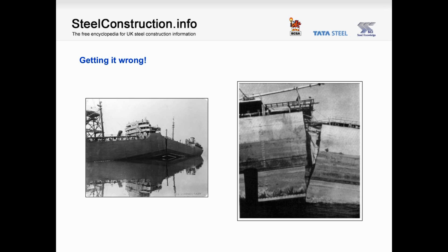It's also worth noting that there'd been a technological change in the shipbuilding industry at the time, and riveting was starting to be replaced by welding. And initially, the finger was pointed at this for the failure. However, a lady called Constance Tipper at Cambridge University did some research and discovered that the cracks occurred not because of the welding, but because of the grade of steel.